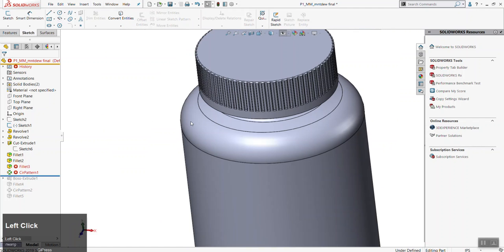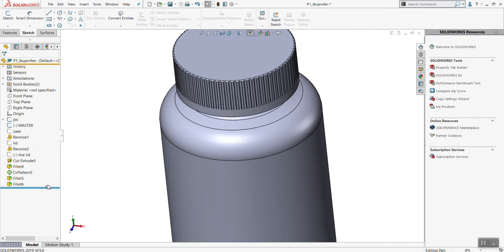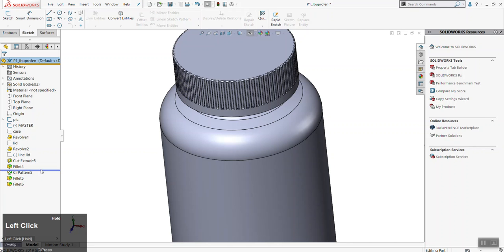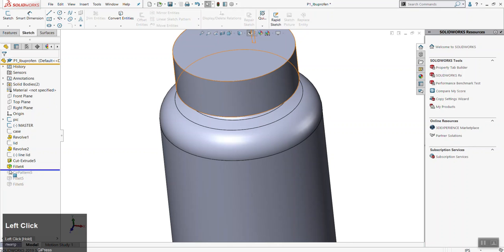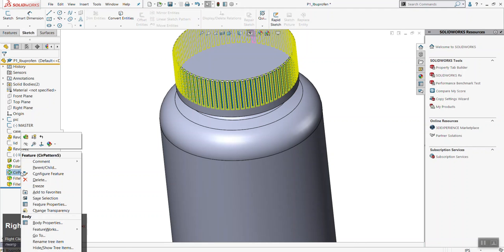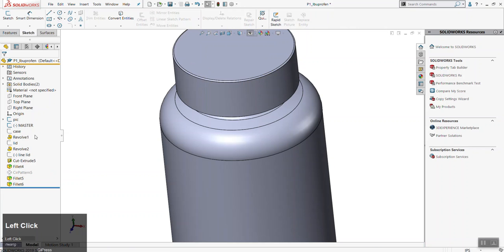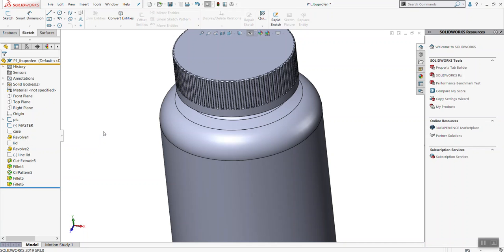I realize we're cutting this close now. Just so everyone can understand what Nina said, she was dragging this bar up to suppress that. I see that it's in here. I just wanted to show you all that you can right click on this and say suppress. It's like a light switch that turns it off, and it's still in there. You can right click and turn it back on. Hiding is visual. This is actually a switch on the command that turns it off.